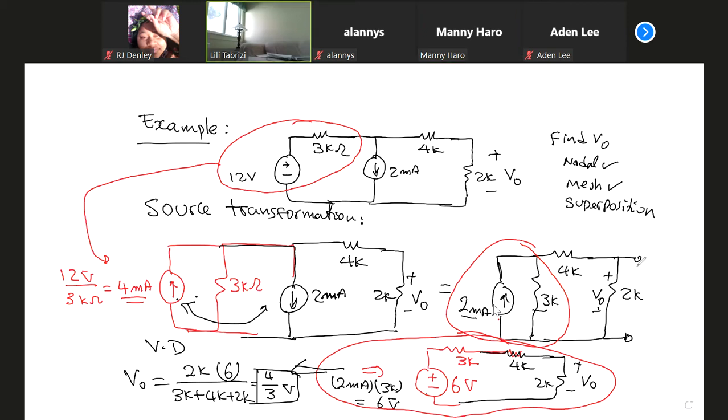Yeah, because an open circuit has no current. Usually when they extend the line, that's just the style they use in textbooks. They just want to show that it's not connected anywhere, because this side doesn't draw any current. That's why this voltage remains the same. So if I put plus or minus V0 here, it's the same as this one. Okay, thank you.